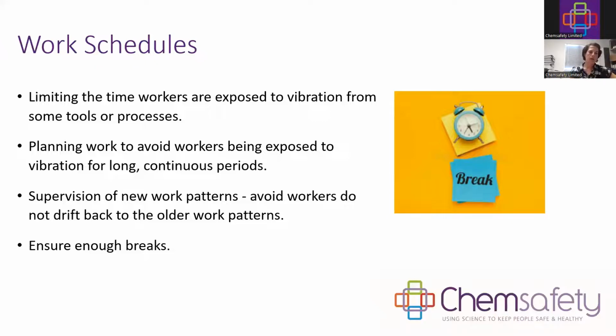And then also, it's important to plan the work ahead to avoid workers being exposed to vibration for long continuous periods. So say, for instance, you have to grind a large frame. So knowing what you are going to do today, having a plan in place reduces the risk in the sense of they're going to grind for 30 minutes, they're going to finish that section of the job, and it is done, instead of going to the frame, grinding a bit, coming back, it doesn't fit, then they have to go do it again. And that in the long term increases the vibration risk.